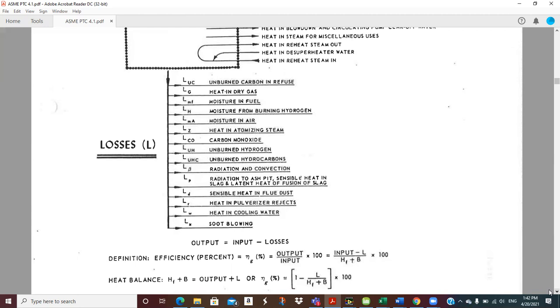Okay. Well, we know when we did some of the little combustion analysis, we saw that the coal had moisture in it. And so that's probably in the liquid form, bound up in the coal particles, right? And as we burn that, the liquid water is going to vaporize, and then it's going to leave as vapor. If it comes in as liquid, that's not much energy wise.